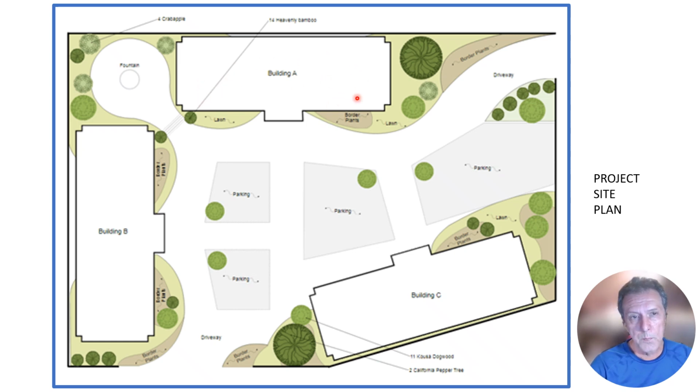Maybe this part of the site is lower, so this needs to be built up with fill to the finished floor elevation for building A. Maybe this building is on a higher elevation, and so the ground needs to be cut down. So in the paving area, that has to be treated differently from the buildings, because the buildings, of course, will require foundations. Maybe they'll require deep foundations, so you have to drill down to a certain depth to get samples and to judge the condition of subsurface soils and bedrock.